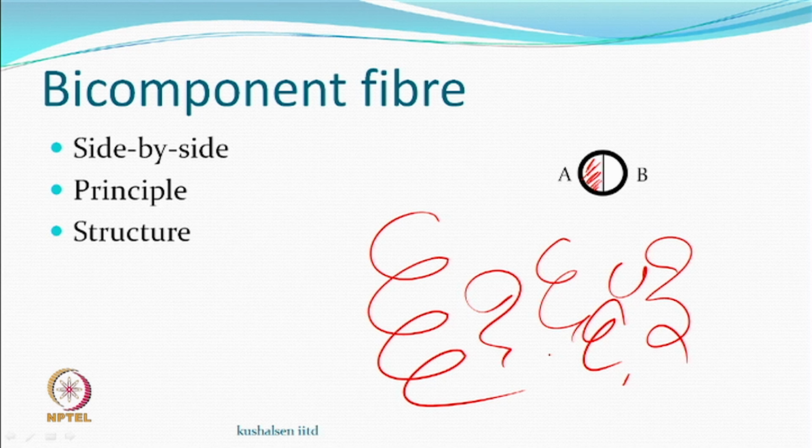One of the interesting products which we had was the acrylic bicomponent spun yarn system, where you would say it is a bulky yarn, right. But if you are very smart and the difference between the swelling capacity of A and B is so large that they actually make a beautiful helix, you can see that. The helical structure is not there, it is here, a little bit of a difference.